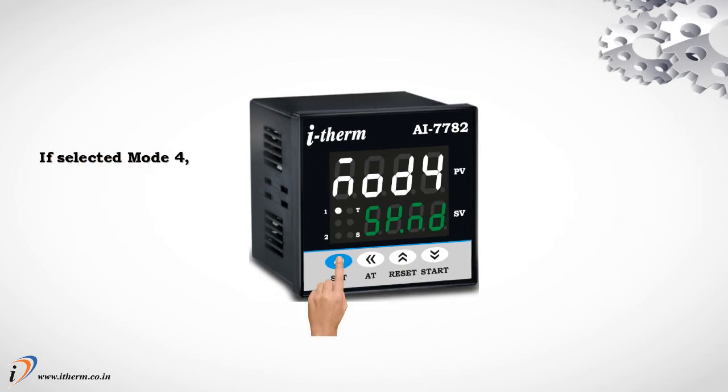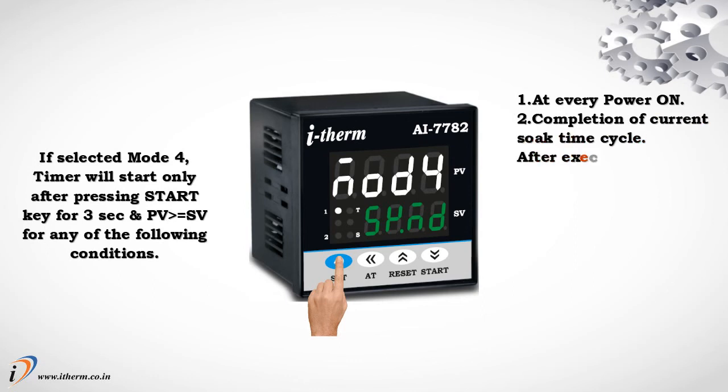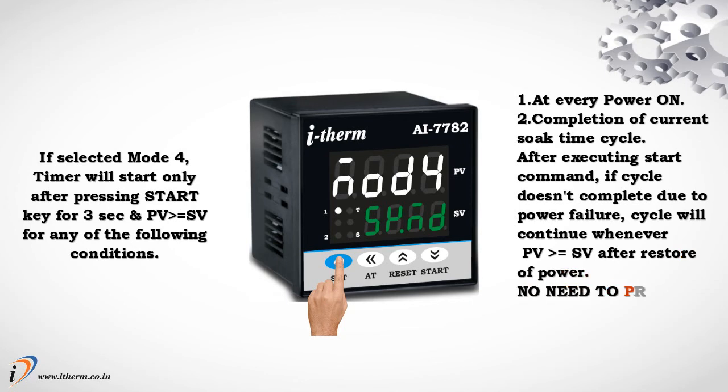If selected mode 4, timer will start only after pressing start key for 3 seconds and process value is greater than or equal to set point value for any of the following conditions. 1. At every power on. 2. Completion of current soak time cycle. After executing start command, if cycle doesn't complete due to power failure, cycle will continue whenever process value is greater than or equal to set point value after restore of power. No need to press start key.